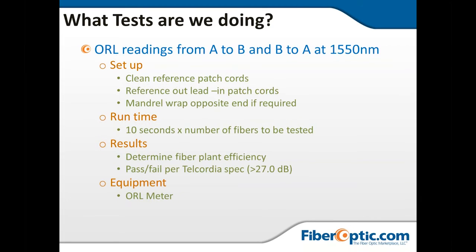Now, optical return loss. Optical return loss is a measure of all returned light, whether it's backscatter or reflections at connections. It's a measure of all returned light. So our setup on our ORLs, we're going to clean our reference cords, of course.